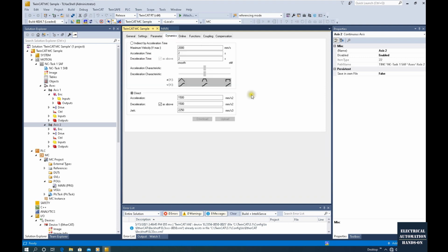And let's go to the dynamic. If you find your motion system's acceleration and deceleration need to be optimized a little bit, you can adjust this, depending on your actual hardware behavior. For example here, if we drag this block in this direction, that makes the acceleration and deceleration lower than before. So the system is smooth, but slow. And if you want your system to be very aggressive or very active, you could enlarge this. It depends on your mechanical system performance, and also on the motion performance you want to reach.